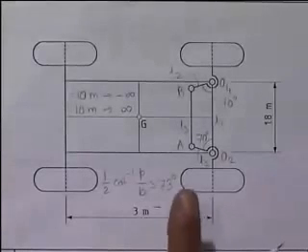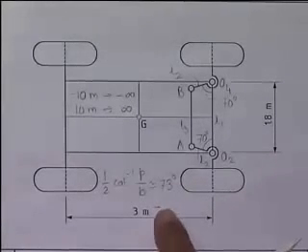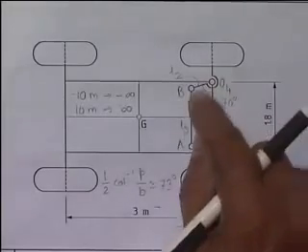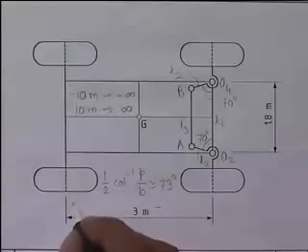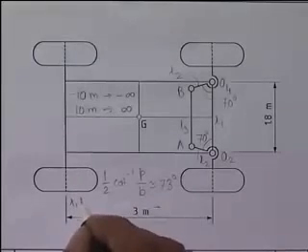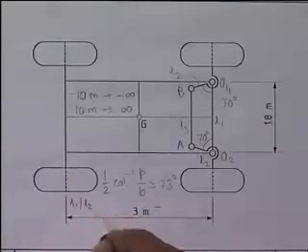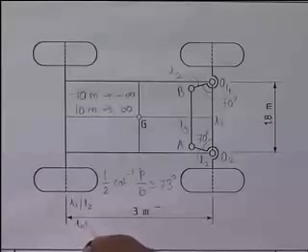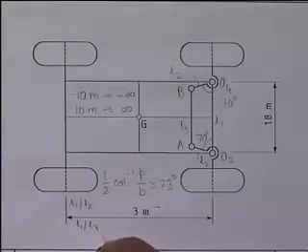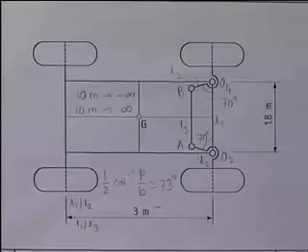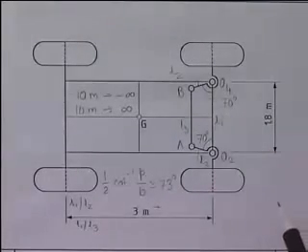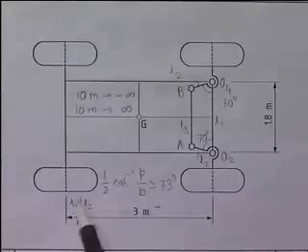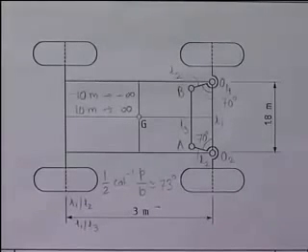And we have only one accuracy point to solve for, because we have already taken this as one of the accuracy points, and there are only two link length ratios, namely L1 by L2 and L1 by L3. So we can satisfy at the most only two accuracy points. One of the accuracy points corresponds to the straight configuration. That leaves us only with one further accuracy point.